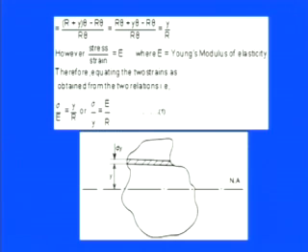If you compare this with the realistic bending of a beam, you will find that as you move from the neutral axis toward the upper surface, you have more and more stresses. This also follows from the formula sigma equals E by r into y. As you increase y, you have more and more bending stress in the beam, and the fibers at the extreme corner experience the maximum bending stresses. We will describe many more things in the further lecture.